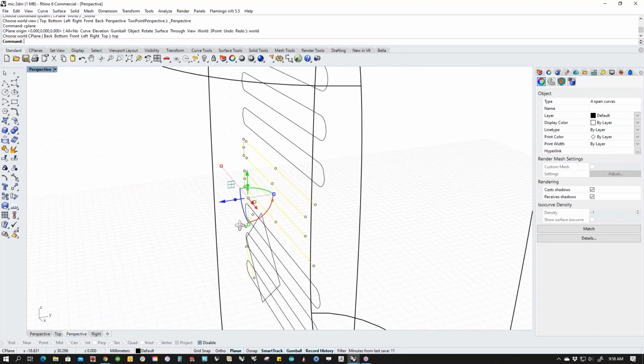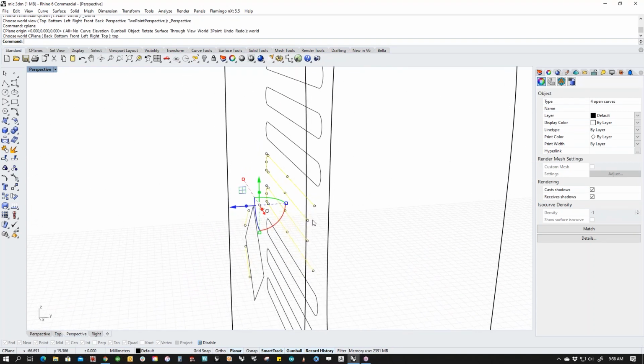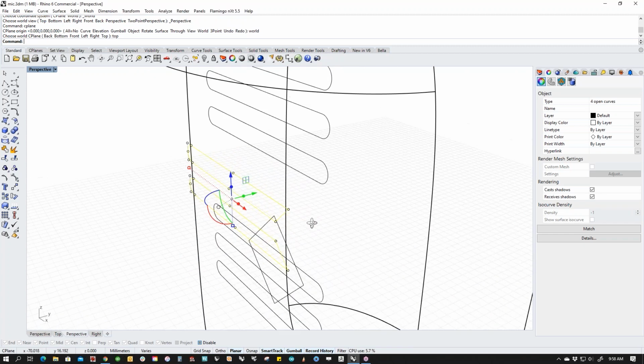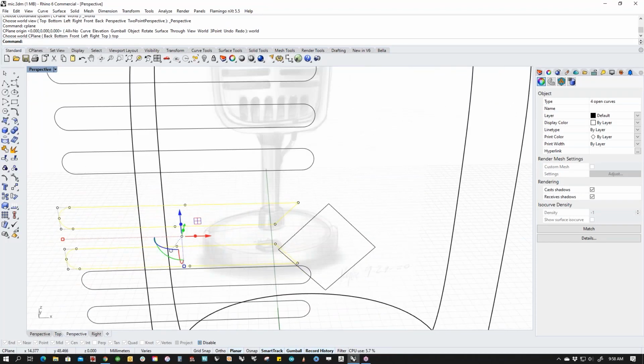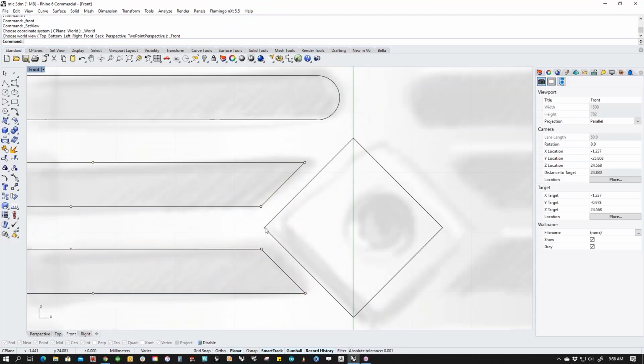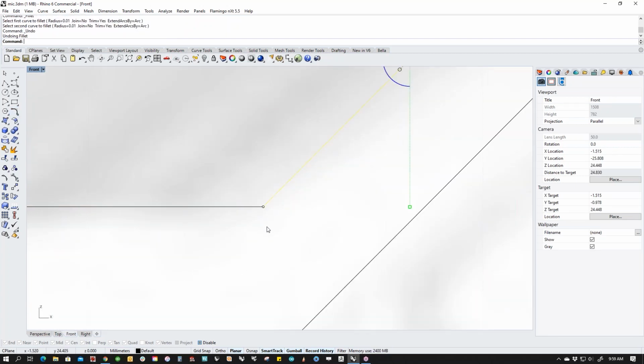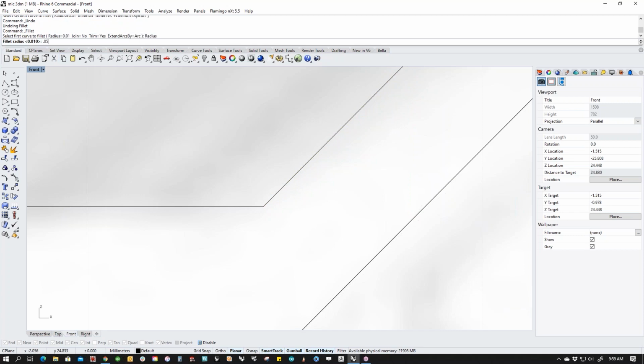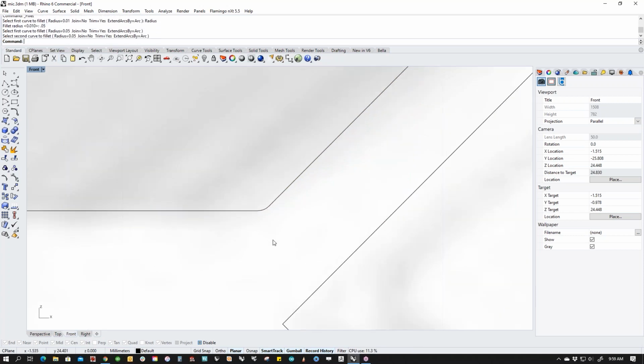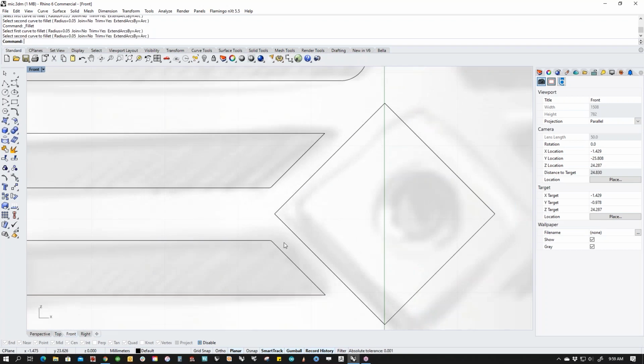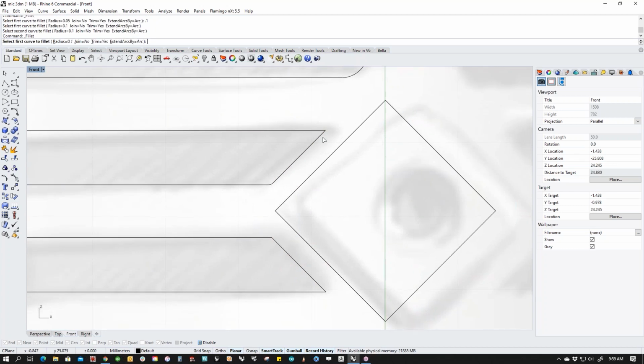So let's grab them. See how my curves for my square up here, my curves for my projector back here. I'm going to fix that by just scaling them together using gumball. See how they jump together like that? If you scale to 0, everything meets in the middle. And then let's try this again. And that worked. That's a little too small. That's better. Actually, that's still too small. There we go. That feels better.